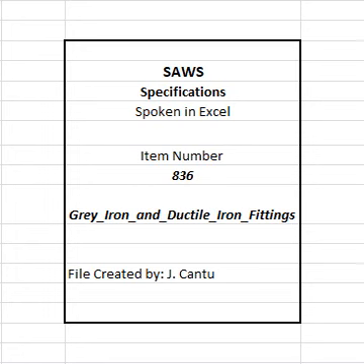A. ANSI A21.4, AWWA C104, Standard for Cement Mortar Lining for Ductile Iron Pipe and Fittings, for Water. B. ANSI A21.10, AWWA C110, Standard for Ductile Iron and Gray Iron Fittings, 3 inches through 48 inches. C. ANSI A21.11, AWWA C111, Standard for Rubber Gasket Joints for Ductile Iron Pressure Pipe and Fittings.